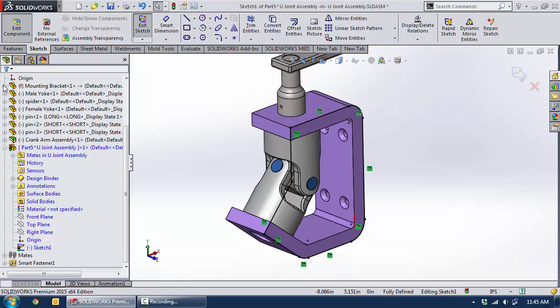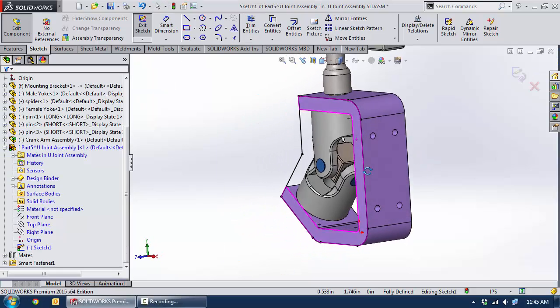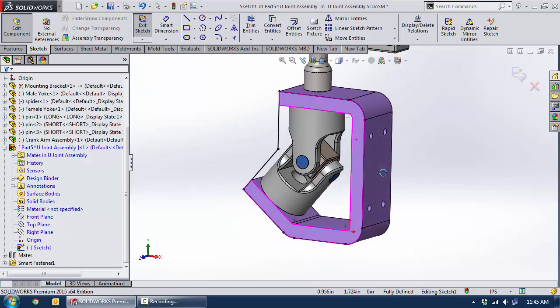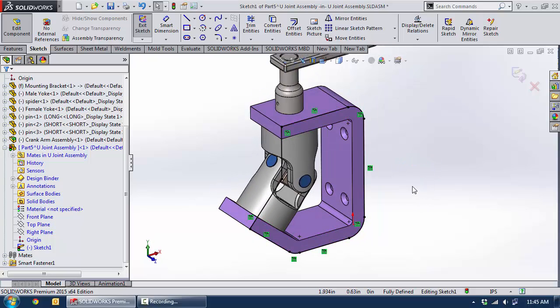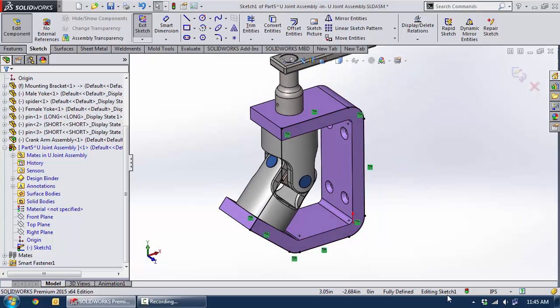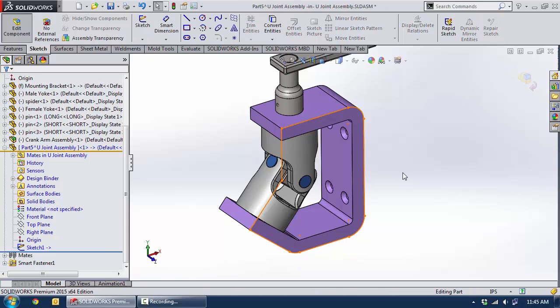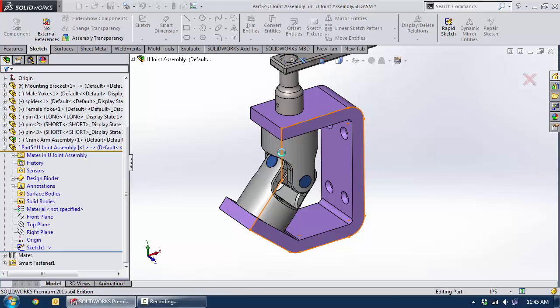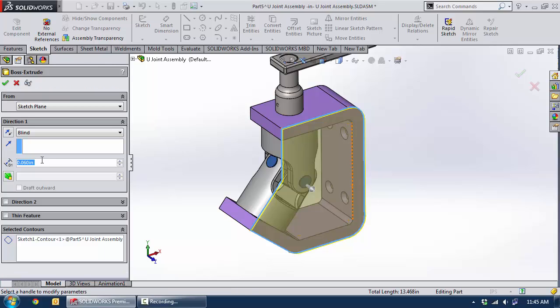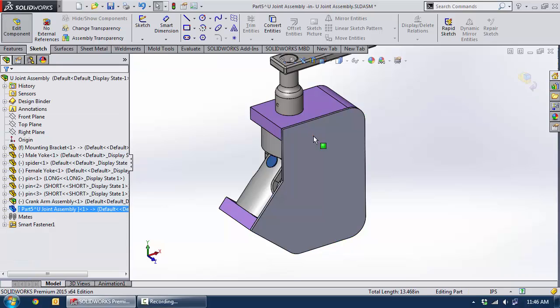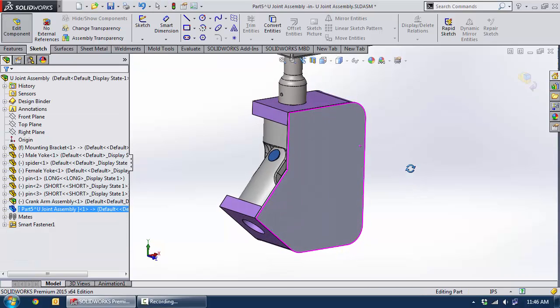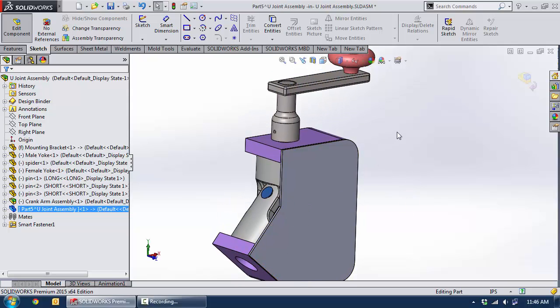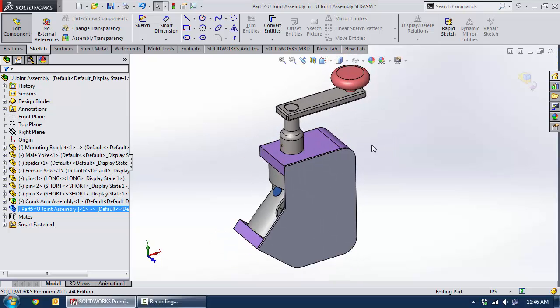and we can now see that I have a sketch that is associated with the outside perimeter of my U-joint bracket. The sketch is fully defined, and I can simply exit the sketch and go in and do my Extruded Boss operation. Give it an appropriate thickness, 60 thou works great, and I now have a cover for my U-joint based entirely on the edges of the U-joint bracket. This cross-part relationship is honored and maintained.